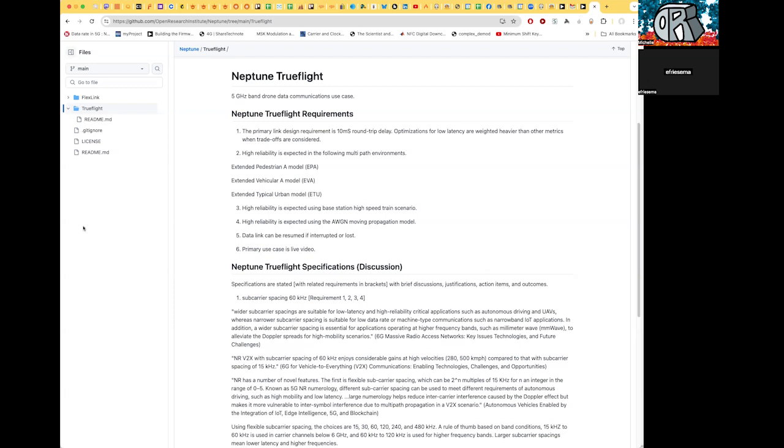And this is where cognitive radio and adaptive signal analysis, or spectrum analysis, is becoming such a hot topic, because with OFDM you have basically a set of bins you can pick, and you can check which ones have the better signal to noise ratio. And with those ones, let's use higher bit encodings. So it's designed in the spec to be very adaptive right from the get-go. It's definitely the most understandable way to deal with reliability, as an inverse of how much interference and signal noise you're getting from the environment. And that's what OFDM was created to combat.